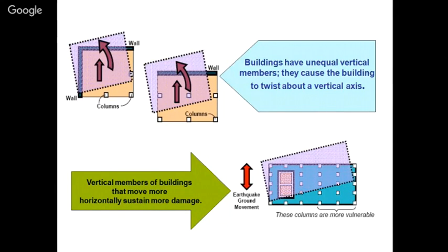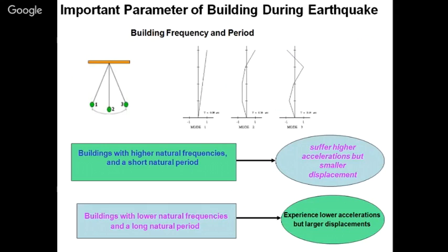For this type of rotational motion, we have to design our columns critically for the forces we are going to develop due to the torsional motion. So we need to avoid these types of conditions as far as possible. If you can't avoid it and you are constructing it, then you have to design it accordingly as per the Indian codal provisions and the forces you get by analysis, keeping all the boundary conditions and specifications into consideration.